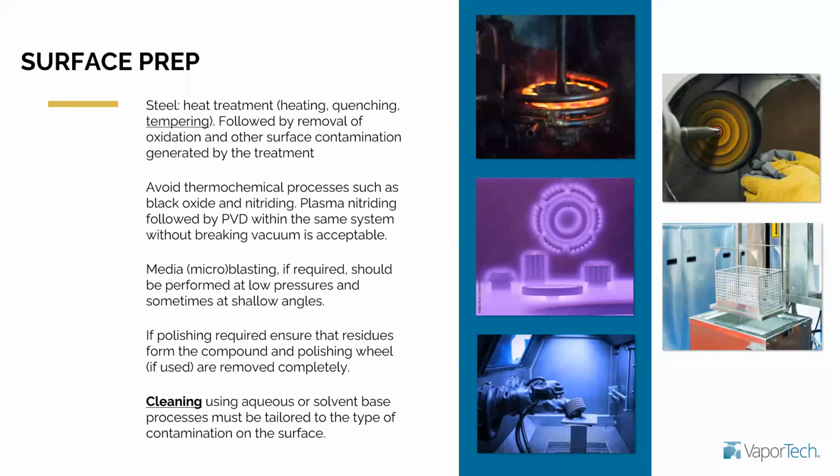It has to be carefully done. Normally you do it at lower pressures than what you would do to just remove heavy scales or something like that. And you might want to use shallow angles as well, meaning not straight at the part, but putting an angle to it to really focus on the surface of the part.